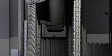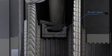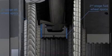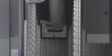assembled on the diaphragm. A brush seal segment is installed on the inside diameter of the diaphragm between the labyrinth seals. This brush seal is in continuous contact with the turbine rotor spacer surface to control the amount of the cooling air passing from the first stage aft wheel space to the second stage forward wheel space. This ensures more precise cooling and better unit efficiency.